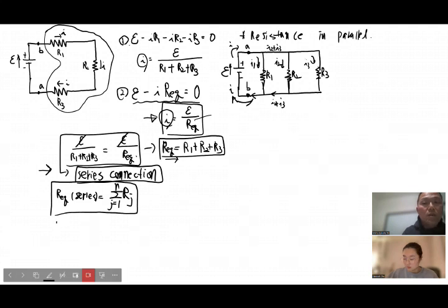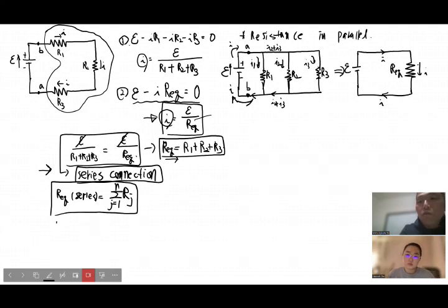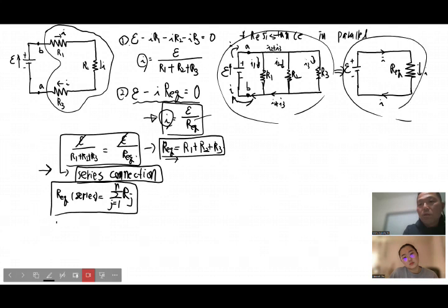So there are three separate current paths connected to these three resistors, and you can convert this model into the simple one-resistor model, the simplified version. If you just imagine there's one big gigantic resistor connected to the battery, that resistor itself will represent the combination of the three resistors. So that is R_EQ, and current goes here and here and here, right? And that is biased with the battery. So these two models should be the same. We have to find the relationship between this net resistor and the individual resistors.